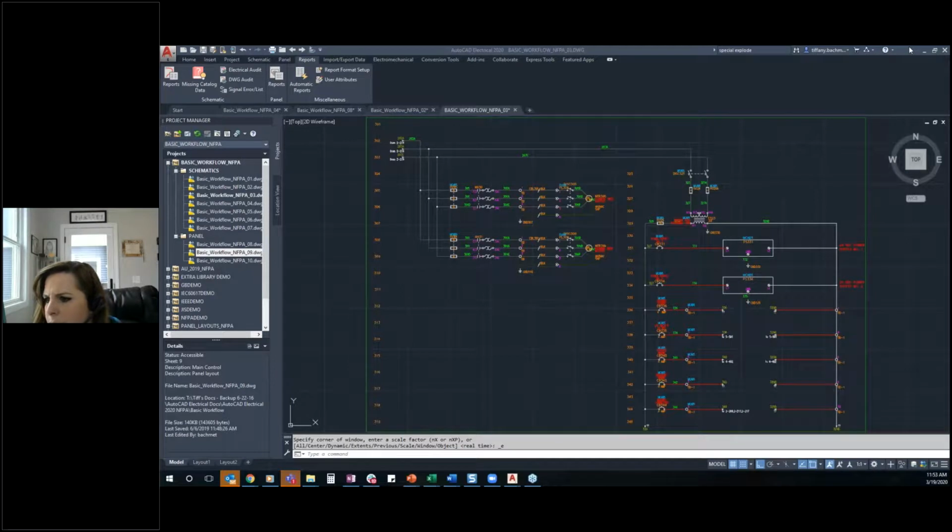Okay, Heath. Any way to reset the wire number format for all ladders in a project? Right now, if the ladder wire number format does not match the drawing wire number format, the ladder format acts as an override, but the only way to find that format differs is if you examine the ladders or notice that the wire numbers don't match the drawing format. Okay.